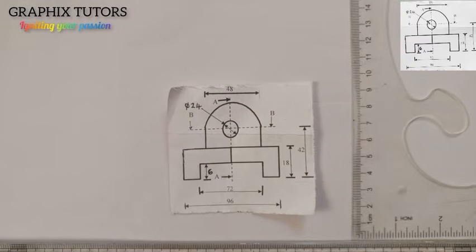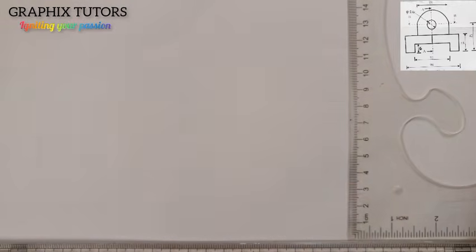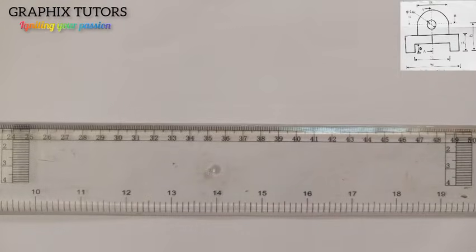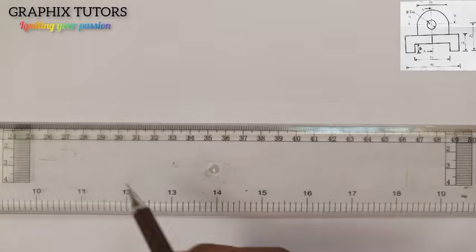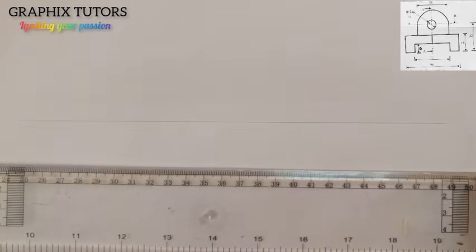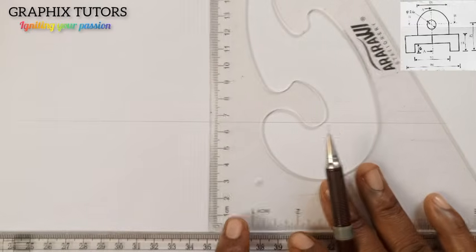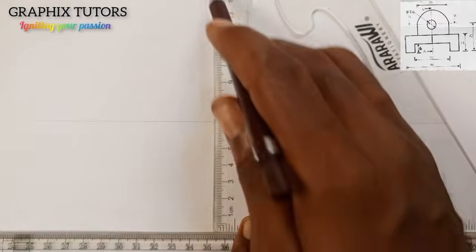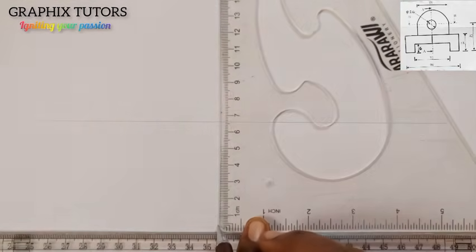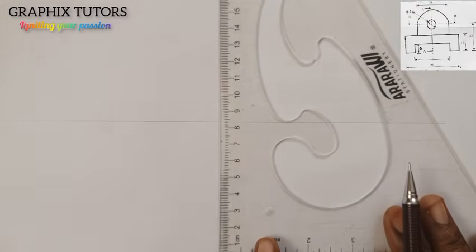So let's see what will happen. The first thing to do in an orthographic projection is to draw your 4 cardinal points. I'll pick up my set square this way, right? My T-square, and I'm going to draw the horizontal line. You can see that, and I'm going to draw the vertical line also this way. That is a vertical line that we have here.